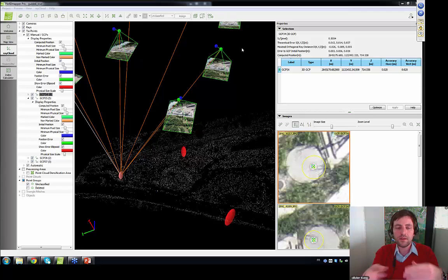So the goal, knowing that we have this 2 to 3 GSD inaccuracy, is to make sure that you fly and take the images in such a way that the accuracy is in something which is reasonable. And this is really about this GSD mostly. Then I would make sure that given this GSD, the overlap values are the best, in such a way that you don't have to use any of the tools that I showed to correct it, because everything will be perfect from the start. And usually something reasonable is to go up to, let's say, 2 to 4,000 images. This is still on the high end of reasonable when you need to assess how many images you need to take.